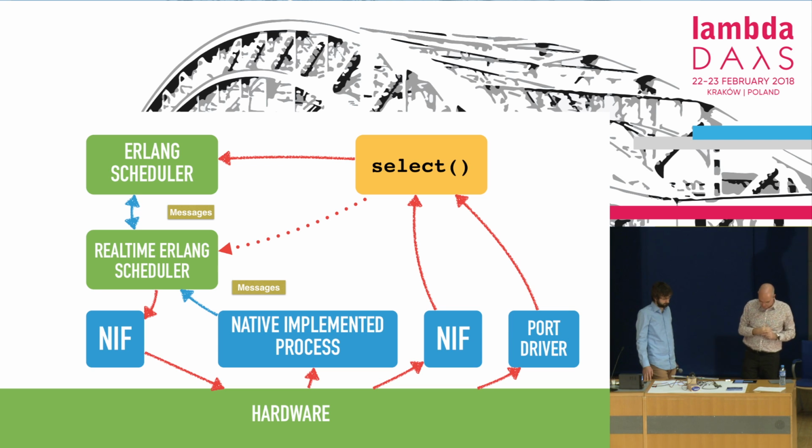So it's always getting priority. To talk to the hardware, to actually write something to the hardware, you can still use normal NIFs, because you go into the NIF, you write to a register, and maybe even read a value from a register and get the value back. This is bounded time. This is not a problem. The problem occurs when you need to wait for something.